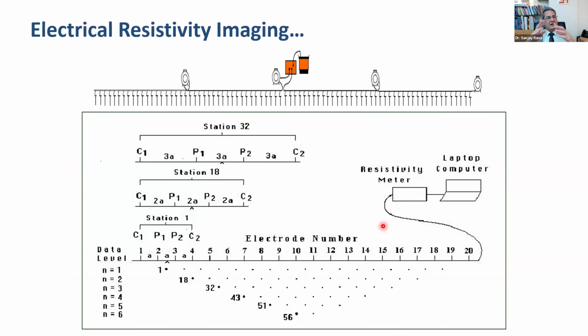Sorry, before I go to that. Seismic refraction method, which we talked about, generally the depth without explosive is limited to 70, 80 meters, not more than that. If you use explosive, you can go even deeper, all right? Now, how deep? Well, Russians use seismic refraction to go up to Moho. That's 29 kilometers. So actually, there is no limit, but generally 100 to 200 meters is what we keep seismic refraction limited to.